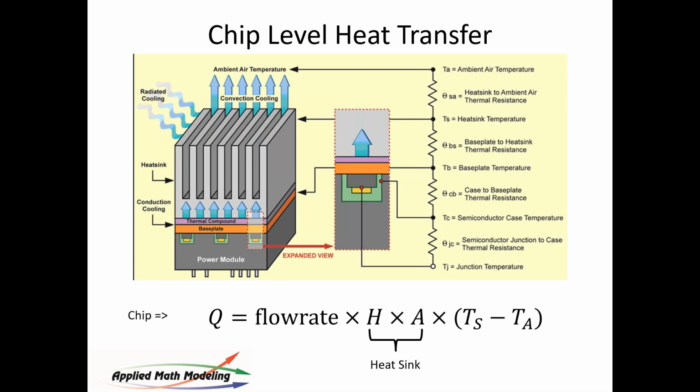And what's been happening with equipment, cooling in particular, of the IT servers is they've been getting better at it. So now they're able to use less airflow. This is a result of improved heat sinks, and I have an illustration of a heat sink here. The heat sink's capability has an awful lot to do with surface area, as you can see here, but also its ability to conduct heat and pass heat through it and get it off that chip. So these things have gotten better.